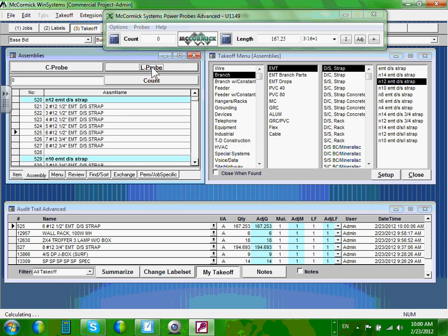Okay, before I let go of this area, guys, we have taken, and you continue doing the same thing. So for our project, Ashley, here's the assumption, because you need to take off. Assumption: we're using EMT conduits. So you're going to take all the branch circuits as EMT conduits. Now, though we have feeders, remember the feeder, guys? Let's do one for the feeder, okay?